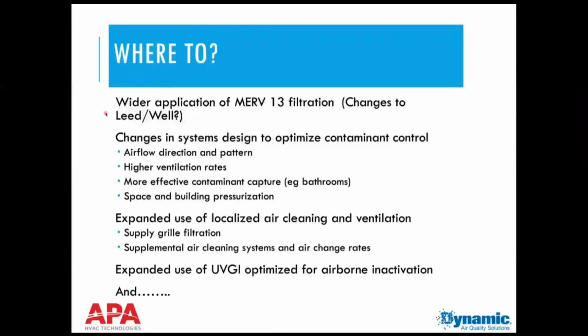I think that, whether it's upper room UVGI or other localized systems, people may have an increased use or desire to have those kinds of visible systems in a space, if for no other reason, again, the psychological reason. It's like, oh, look, there's my air cleaner, I feel better. Same with putting filtration in supply grills, in addition to what's in the air handler. Because when you think about critical environments, clean rooms, operating theaters, the biggest hammer is right before the air goes into the space. It's not 60 feet away at the air handler. You've got filtration there too, but your high efficiency filtration is right before people are going to breathe it or have to go over their operation.